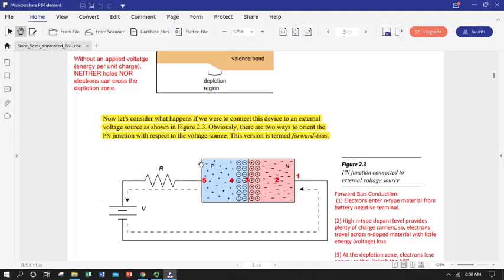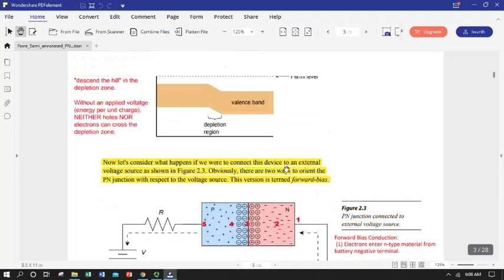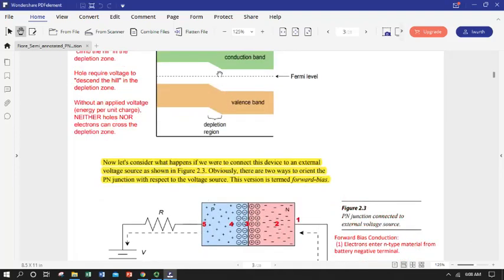One thing you can imagine in that case is all of the positive charge carriers in the P are going to get attracted to the back lead that's now negative and pulled away from the interface. And the same with the negative. And in so doing, what we actually do is make this hill huge. It's huge and no charge can cross it.